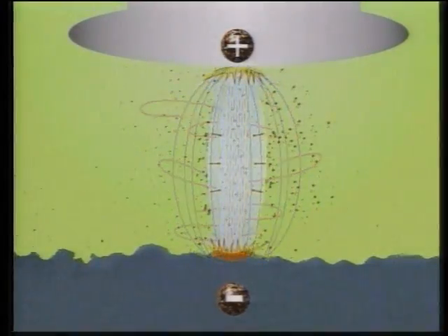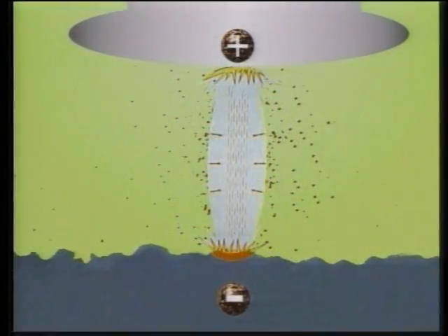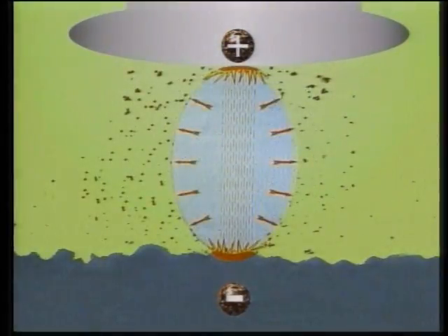As the field's voltage increases, this material in the conductive bridge heats up. Some pieces ionize to form a spark channel between the electrode and the workpiece. At this point, both the temperature and pressure in the channel rapidly increase, generating a spark. A small amount of material melts and vaporizes from the electrode and workpiece at the points of spark contact.